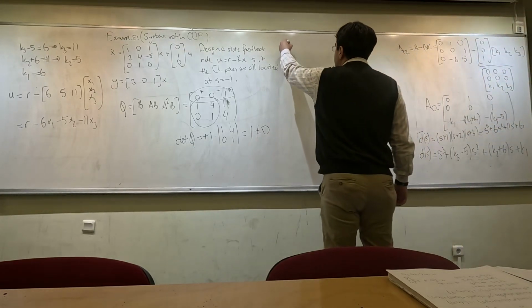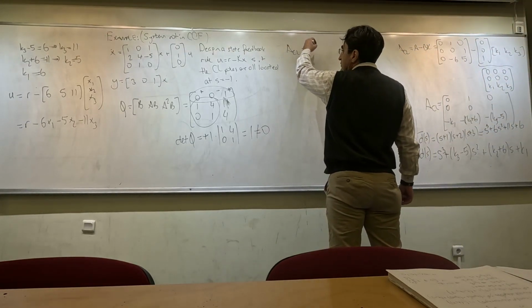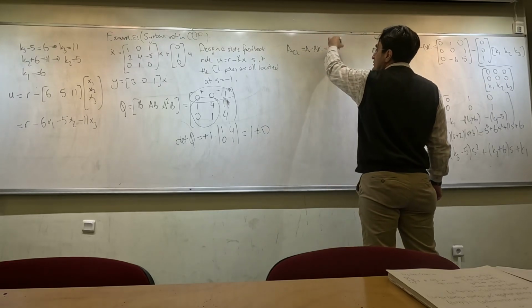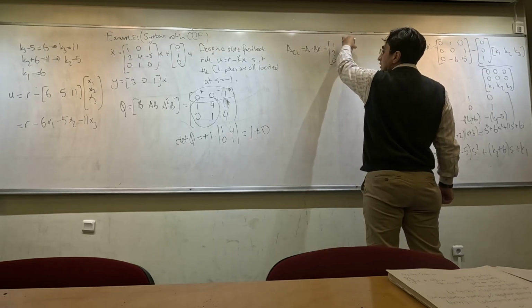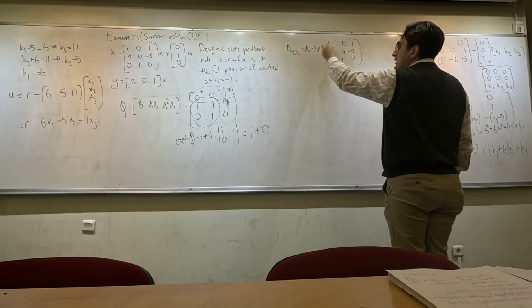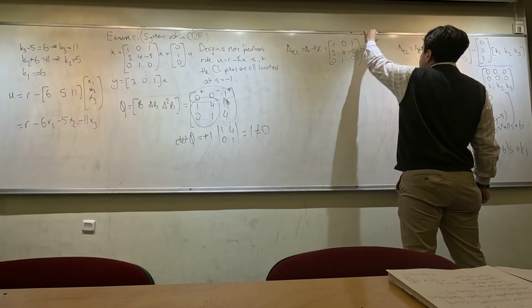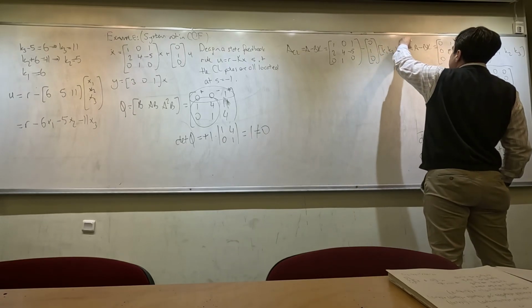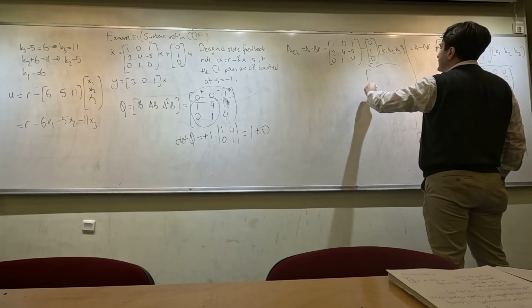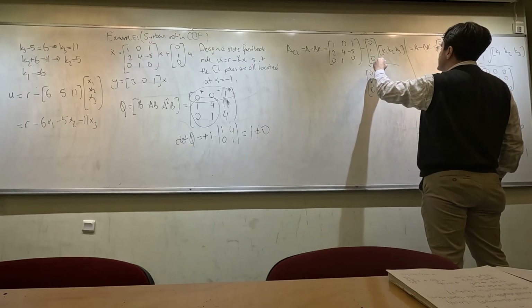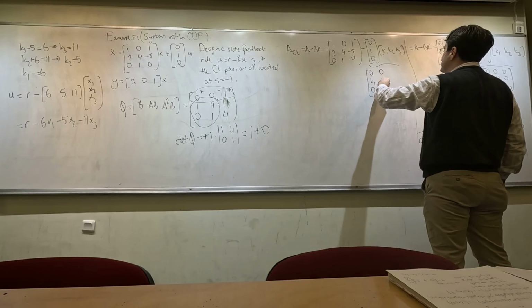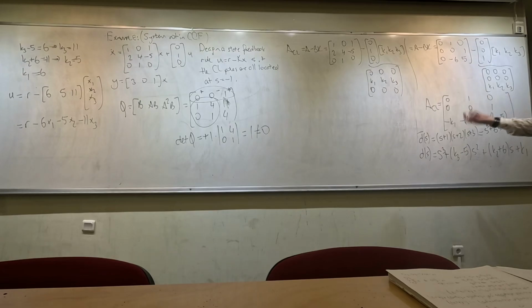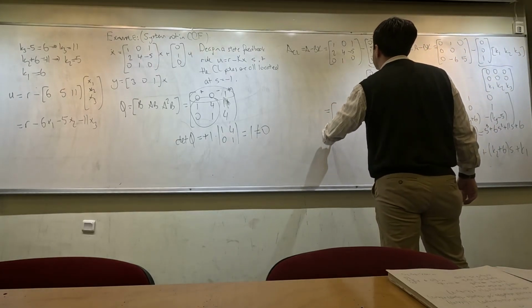So now I can look at my design. I will calculate here the closed loop A matrix. A closed loop is A minus BK. And here A is [1, 2, 0; 0, 4, 1; 1, -5, 0]. Okay? And I have minus, B is [0; 1; 0], and I have here K, [k1, k2, k3]. And when I do this multiplication, I will get [0, 0, 0; k1, k2, k3; 0, 0, 0]. Okay? And now let us try to do the subtraction.